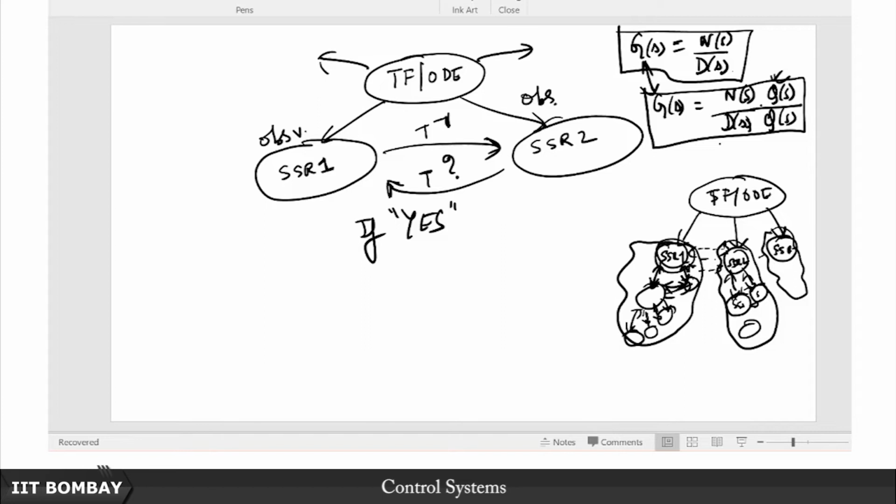So obviously when I am saying it is the same transfer function or same ODE, I am not referring to these. You might, in your bid to prove me wrong, choose these two different representations and say, oh look, at heart they are the same transfer function, after all that Q is common, it will cancel out. But then you better cancel it out, because without cancelling it out, if you want to look for a similarity transformation, it is meaningless, because I will get an A matrix of a size which is different from yours. That is a question related to minimality, which we will discuss in a few lectures from now.